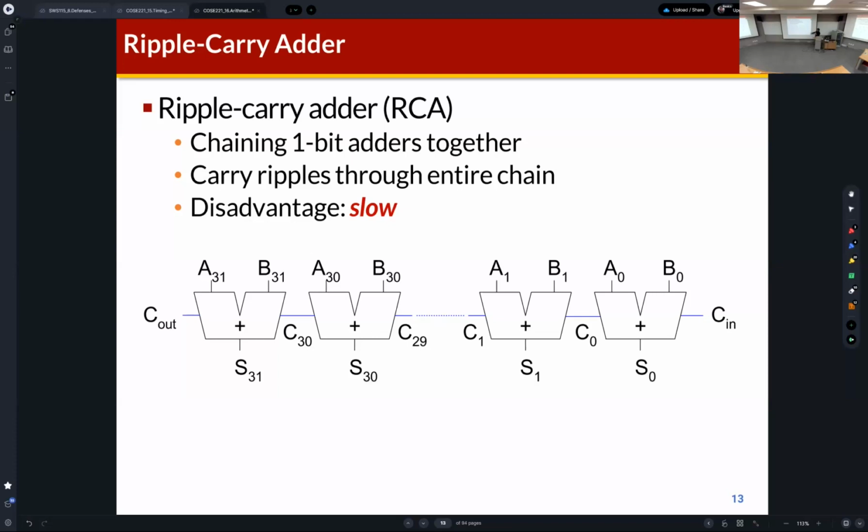Like this, actually. This is the circuit, the multi-bit adder logic that can be built from full adders. This is the LSB, and with A0 and B0 we can generate S0. This adder can also receive the carry-in, and from the LSB the carry C0 is generated. Then this carry is propagated to the next digit, the first digit.